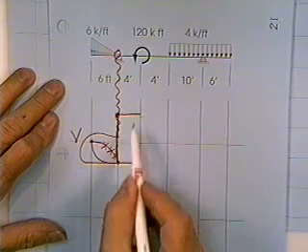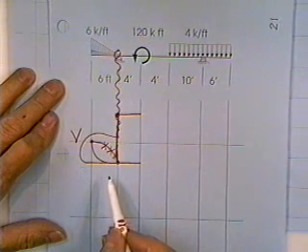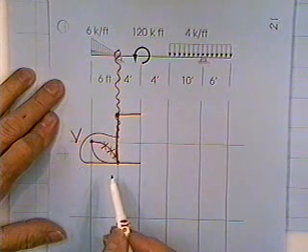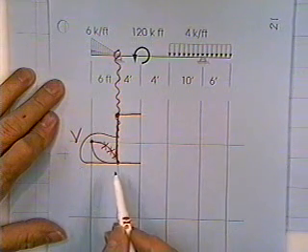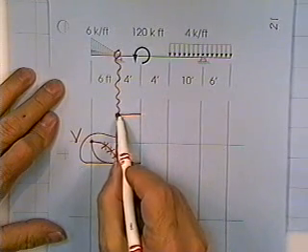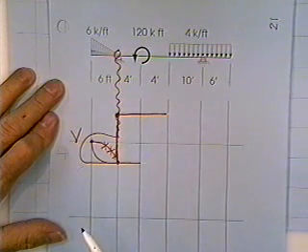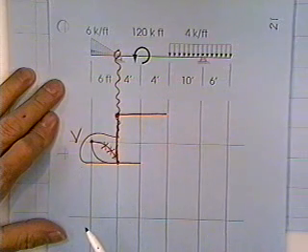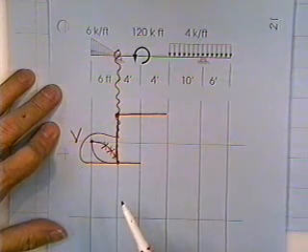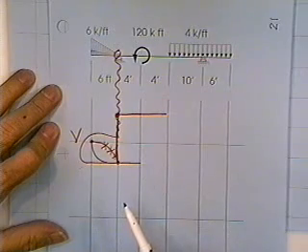Now I go straight across, and as I cross that moment, it doesn't go up like the reaction I missed did. Doesn't go down like the triangle did. Goes round and round. Well, this shear diagram has no place for round and round. Just goes right on across. Don't let it go up. Don't let it go down. It has influenced the diagram. It changed the reactions.